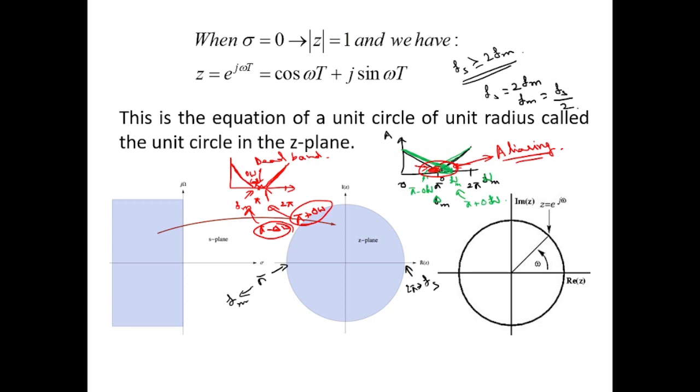So what it does is it eliminates the chances of aliasing altogether. Why? Because under the critical condition fm equals fs by 2, where do you band limit the signal? We band limit the signal in the analog domain, right? By using analog filters. And we already discussed that we cannot design analog filters using the exact calculated resistance and other passive component values. So there will be some deviations.